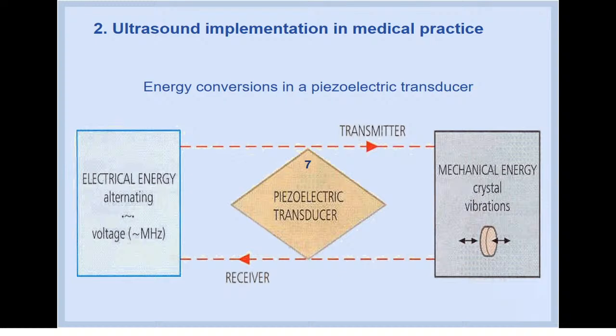But we can say the same about magnetostrictive materials, which exhibit similar behavior but in an applied magnetic field. Both types of transducers also act as a receiver, since the mechanical vibrations produce electric and magnetic fields. They can be detected and used to monitor incoming sound waves.